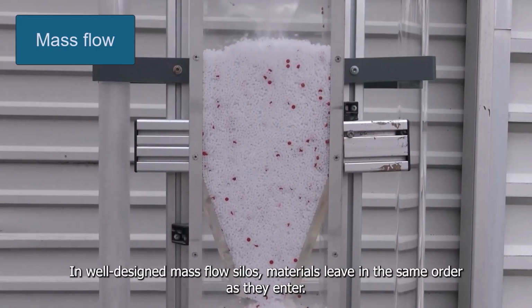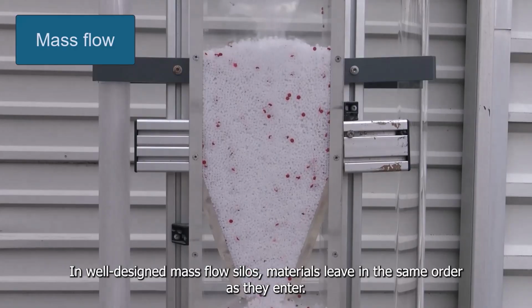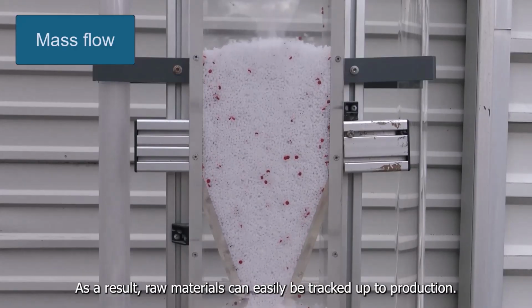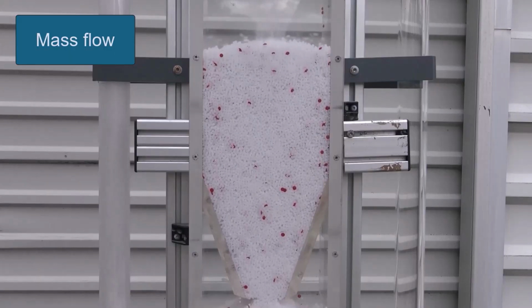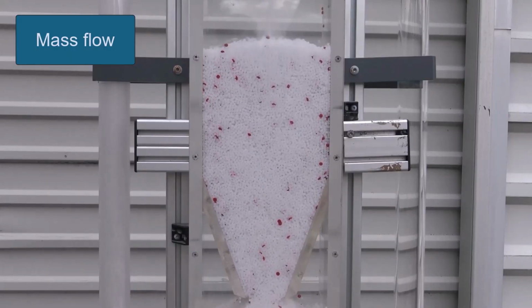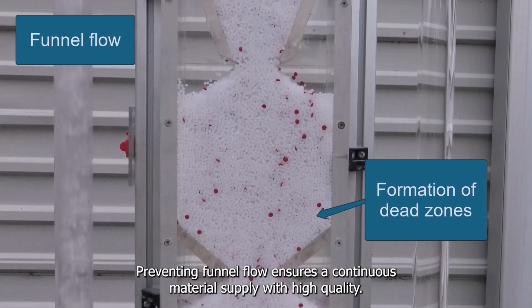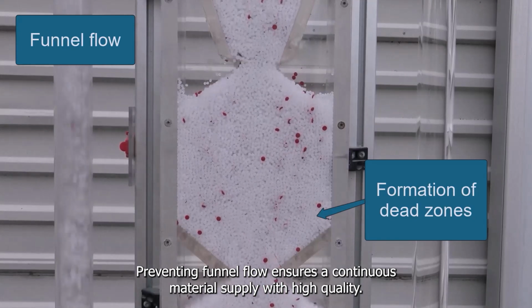In well-designed mass flow silos, materials leave in the same order as they enter. As a result, raw materials can easily be tracked up to production. Preventing funnel flow ensures a continuous material supply with high quality.